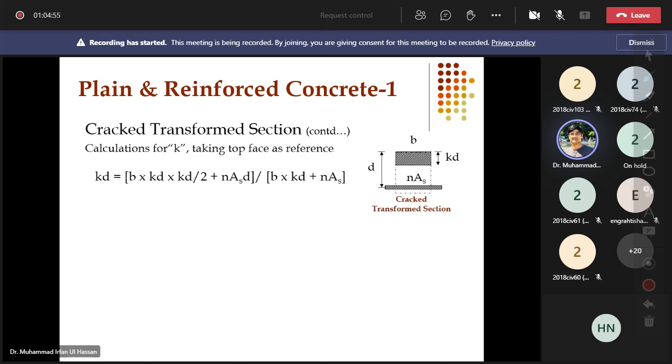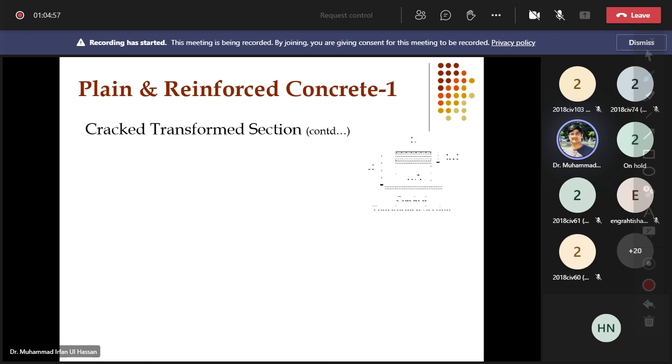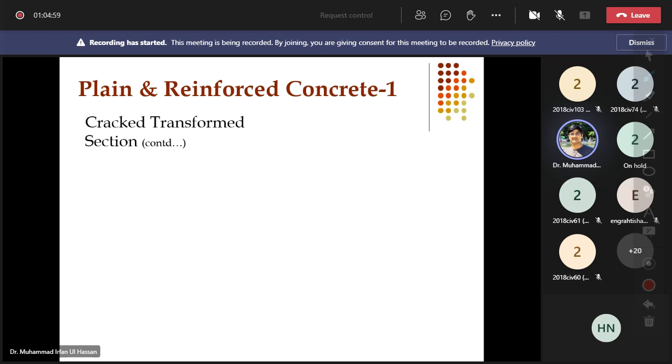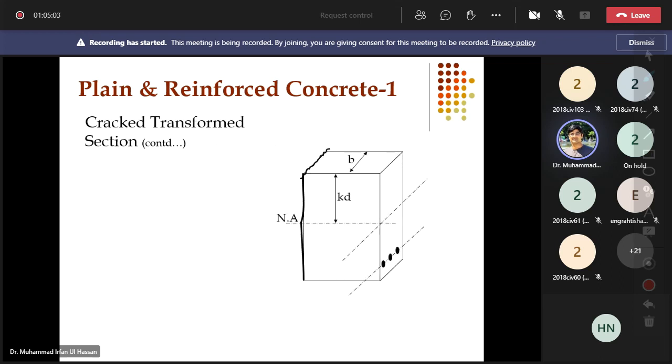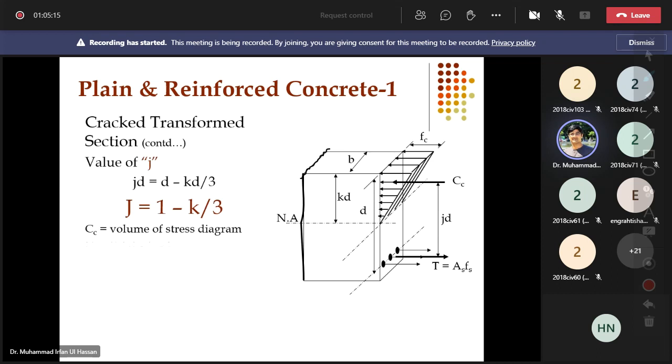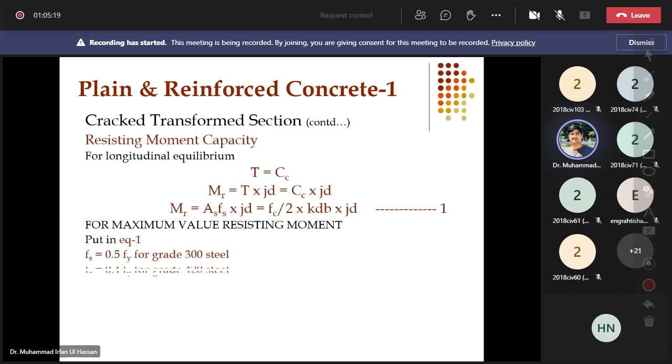So this is an updated diagram, and you have seen that for the singly reinforced beam, the rho you computed is less than rho max, and secondly when ample depth is available, and D provided is larger than the D minimum required, then you can go for singly reinforced beams.